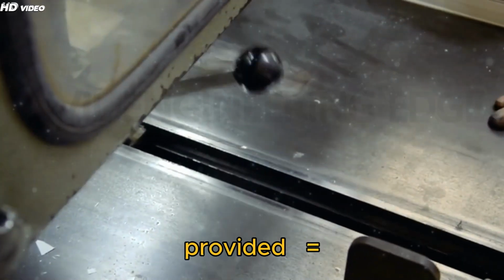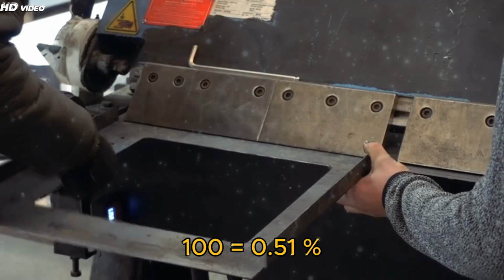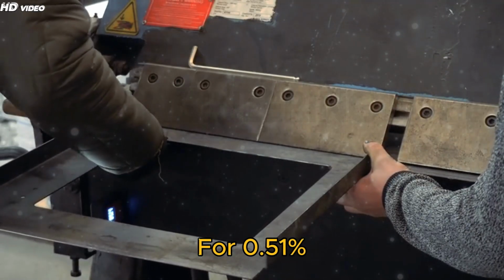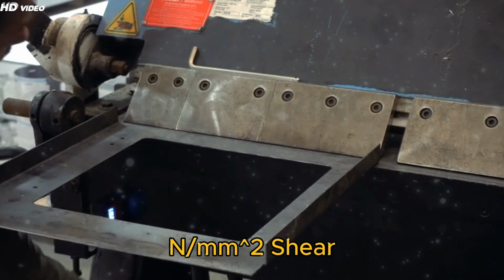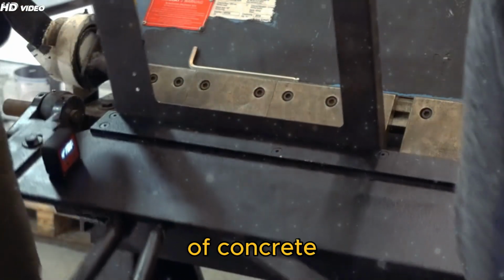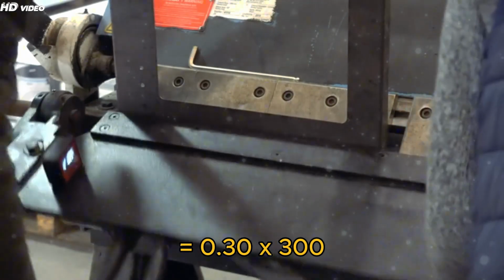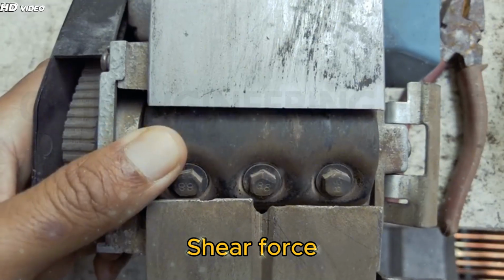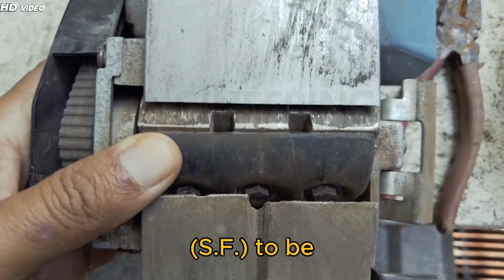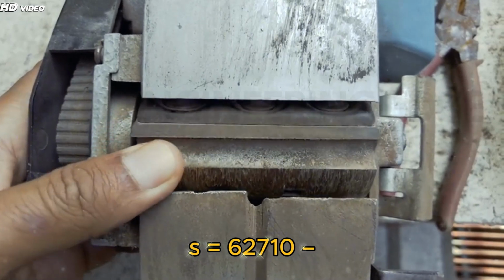Percentage of tensile steel provided equals 1,016 / (300 x 660) x 100 equals 0.51%. For 0.51% steel, p equals 0.30 MPa. Shear resistance of concrete equals 0.30 x 300 x 560 equals 50,400 Newton.